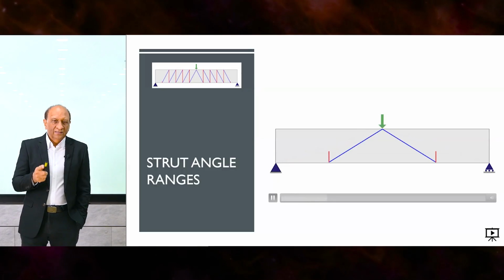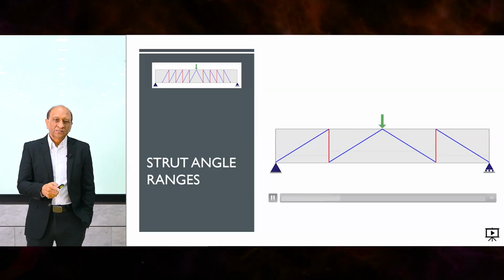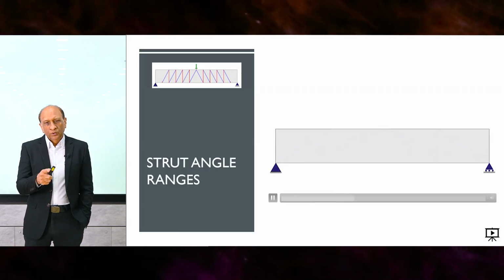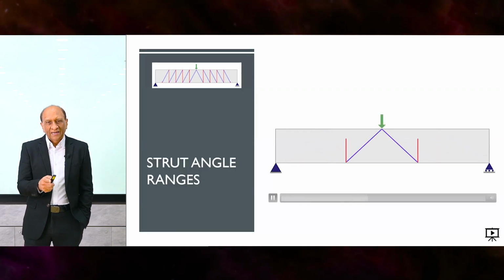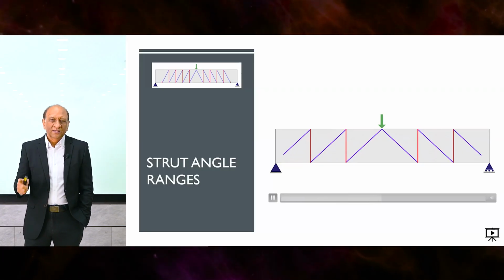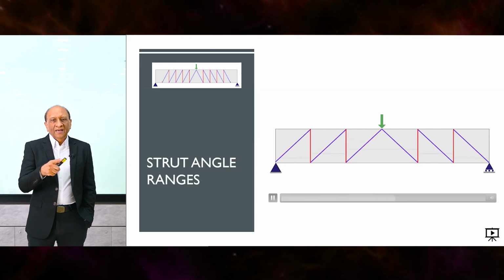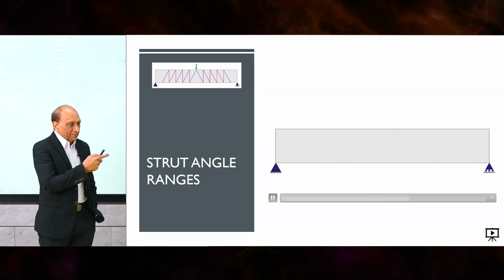And when you draw the angle, you reach the bottom, you take it up, you bring it down. That's how the strut and tie is supposed to work. And this is the efficient way to do that. And then if you want, you can actually do more. You can bring it back at its steeper angle, take up, take down, still did not reach the support, take it up again, bring it back to the support again. So this is another one, 45 degrees. And the next one will be more inefficient because it will give you more angles.